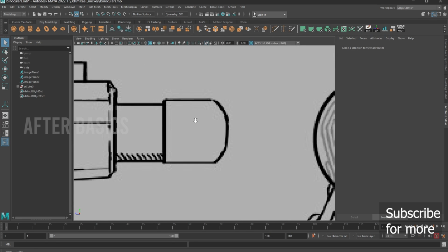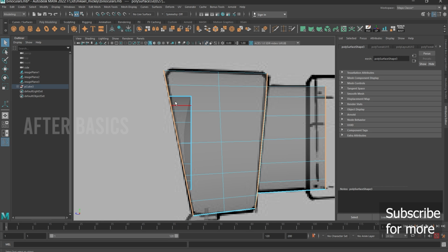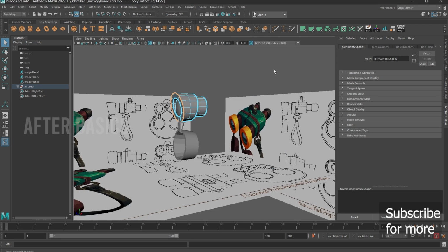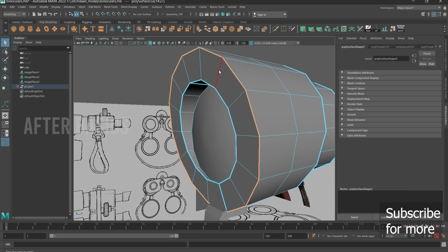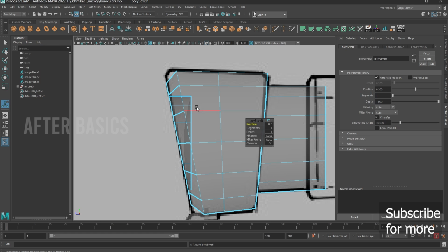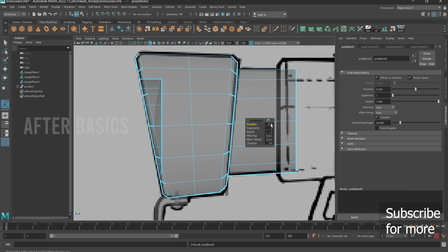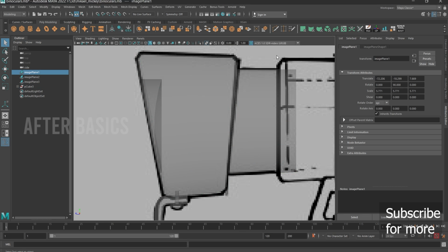So let's go here. Okay, if you are wondering, because we didn't make the dual cut here, right? So let's do it now. So see, you can see the cut shifted to this part, and it's not going to change anything. Okay, so I think 0.2 is fine here. This one also around 0.2. So 0.2, and we are done.